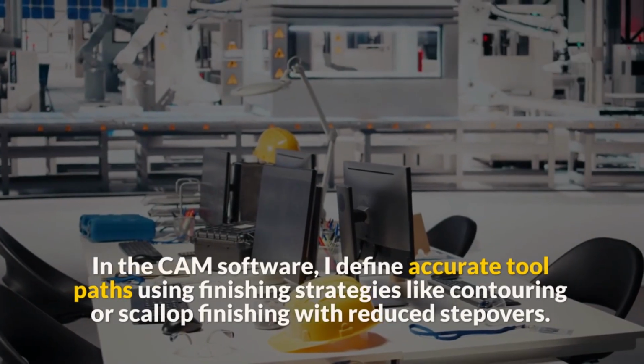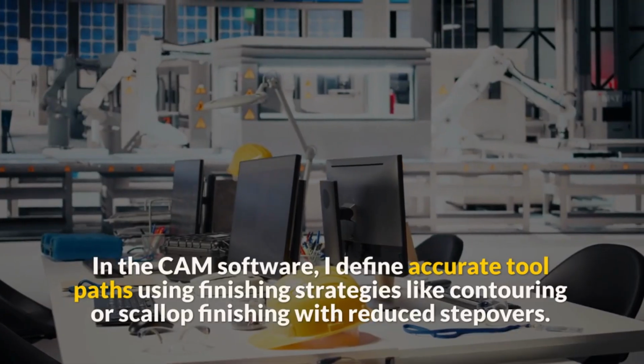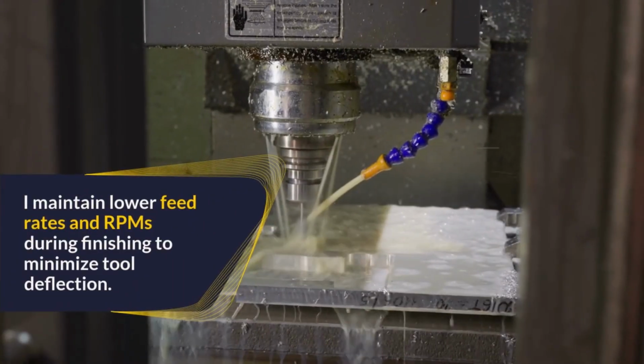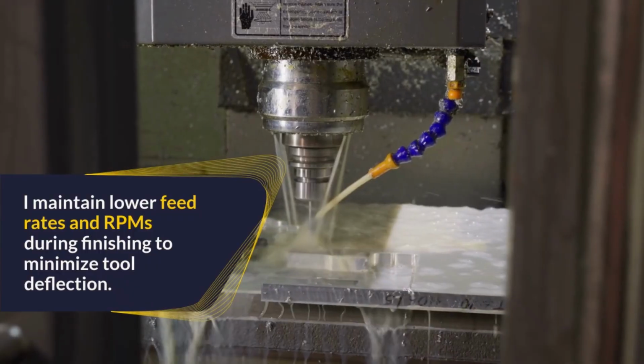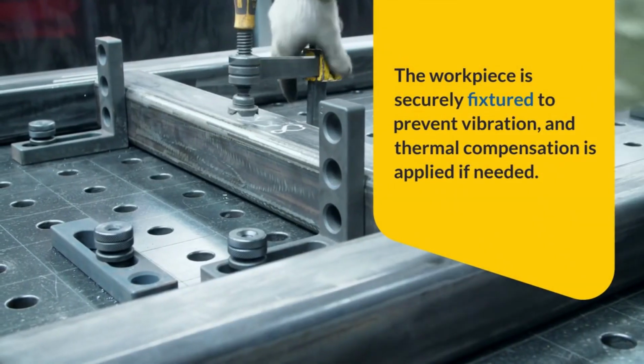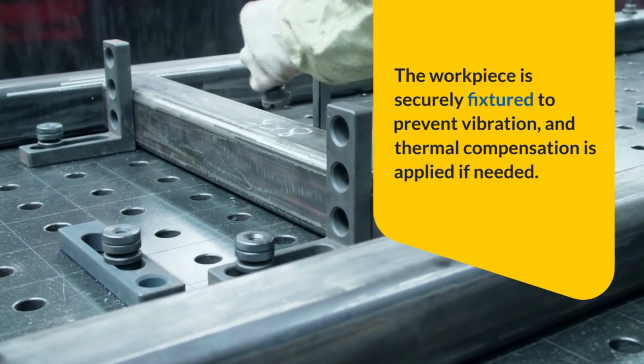In the CAM software, I define accurate tool paths using finishing strategies like contouring or scallop finishing with reduced stepovers. I maintain lower feed rates and RPMs during finishing to minimize tool deflection. The workpiece is securely fixtured to prevent vibration, and thermal compensation is applied if needed.